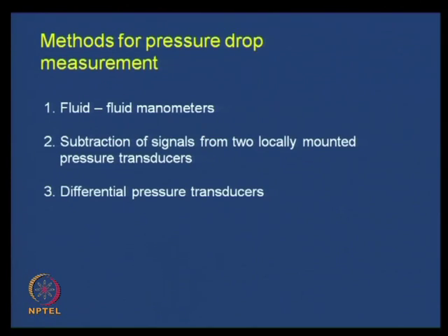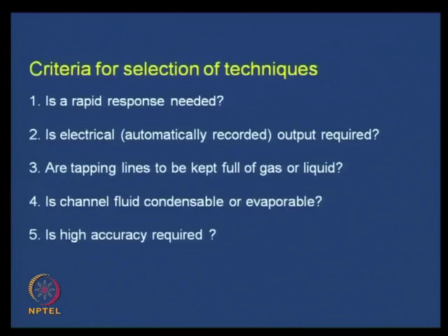We can never say that DP transducers should always be used and others never, or that wall mounted transducers should always be used and the others never. Depending upon our conditions and the application, we have to select a proper technique.